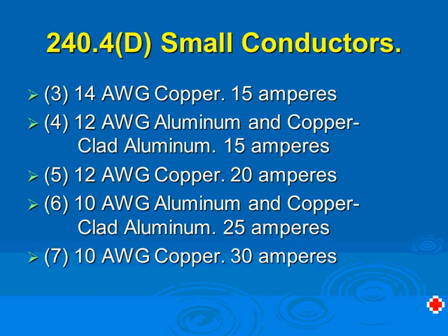So between these, that will cover, I would say, 90% of your lighting circuits and small equipment circuits, as well as your receptacle circuits, which are the most convenient branch circuits. Because they're most convenient, and the public is exposed to them a lot in dwellings and non-dwellings, the code limits the amount of current that can come out of them. Even though, guys, number 12 copper can get you 30 amps based on the code, on the 90-degree column, we don't want to pull more than 20 amps out of it.